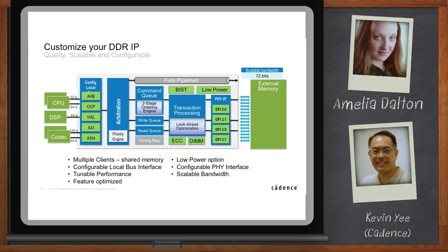And then we support multiple DDR standards. And the beauty of that is it gives you a lot of flexibility. Most of our customers won't just use one. The reason for that is the memory changes and prices change. So a lot of our customers will say, I want a controller that supports DDR4, DDR3, and LPDDR3. Or LPDDR3 and LPDDR2. And what it does is it gives you the opportunity to say, hey, memory prices have dropped for this. So today, LPDDR2 is the cheapest, and I'm going to put that in there, but I can swap it out when LPDDR3 prices drop, and then I can offer a product out there that is higher performance and you haven't had to do a whole new chip design.